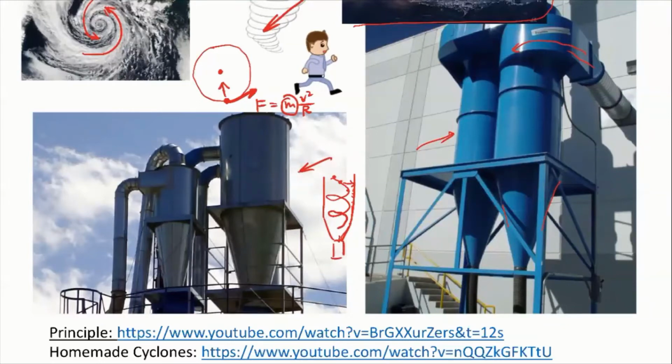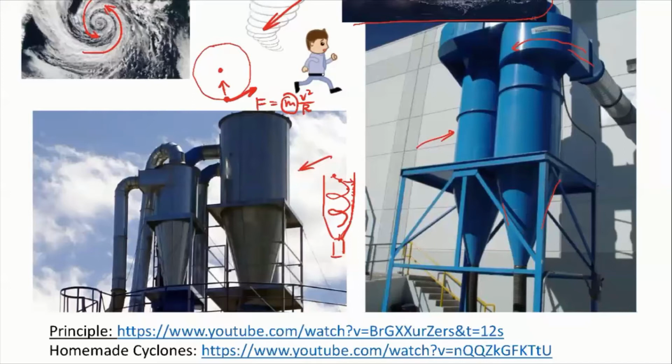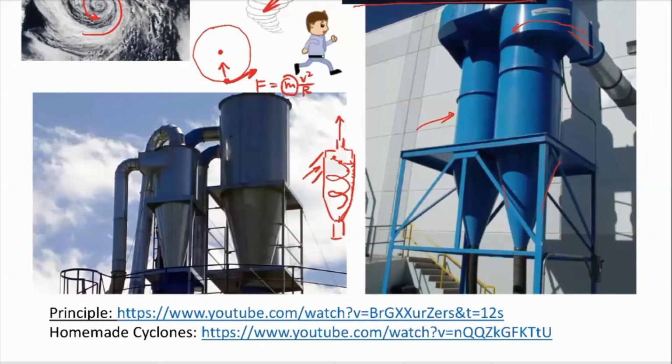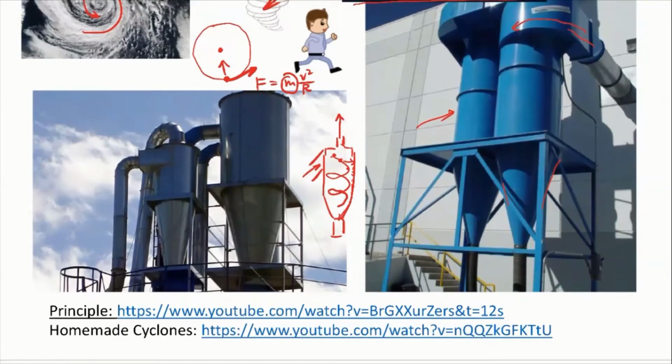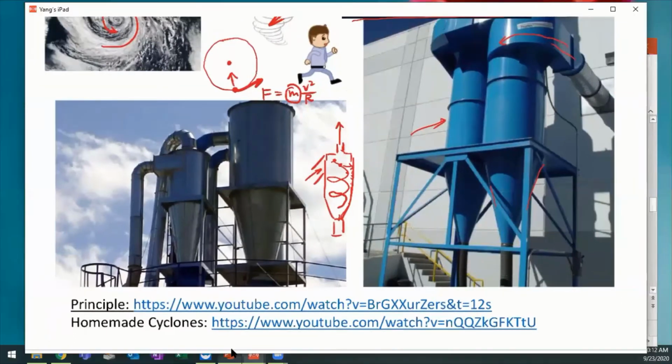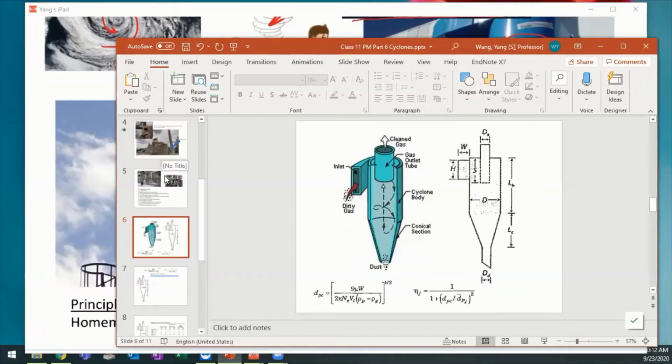And for these devices, typically at the top, there's also an outlet. Okay, so the outlet will draw the airflow outside. So we mentioned that the air will enter from the side and then get drawn outside. In this way, we can basically introduce particles into the system and then withdraw the remaining airflow from the system. So there's a mass balance of the airflow, right? So here I can show you a video about the working principle of the cyclone. Let's do this.